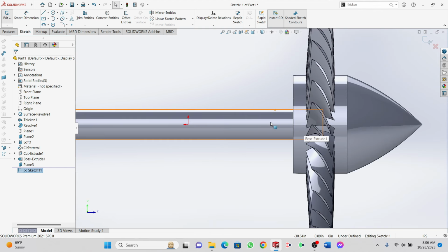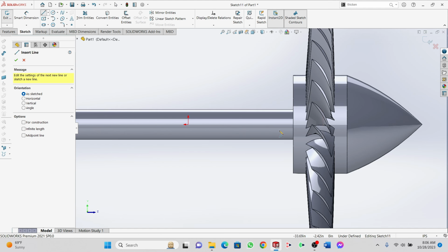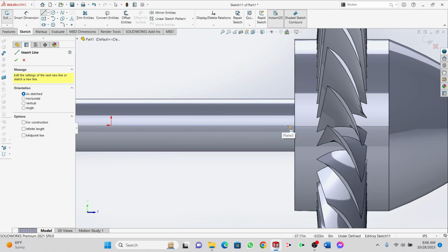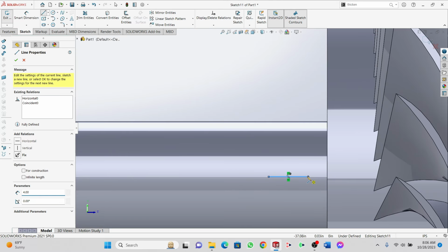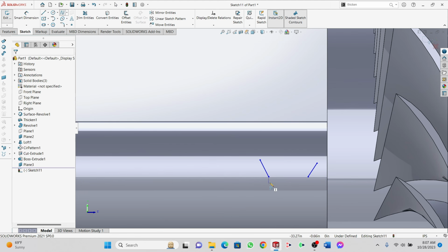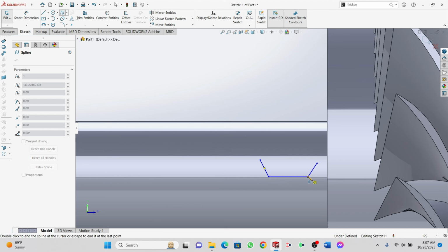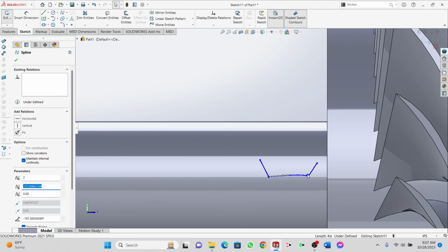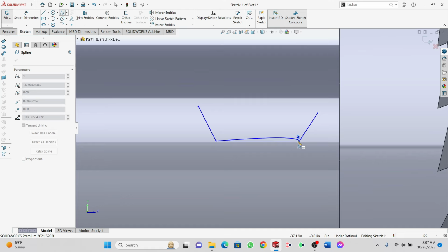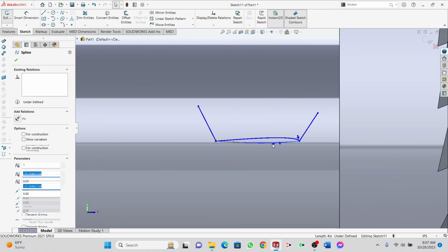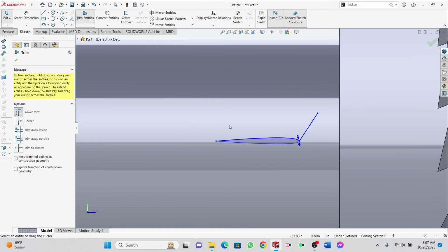So we have to give 4 stages here. So the chord length will be 4 inches. So let's do it. It will be 4 inches. We are making an airfoil. Trim this. Select the spline line from this point to this point. Give it a shape like this and select this spline line and sketch a spline line again. Give it a bend like this.